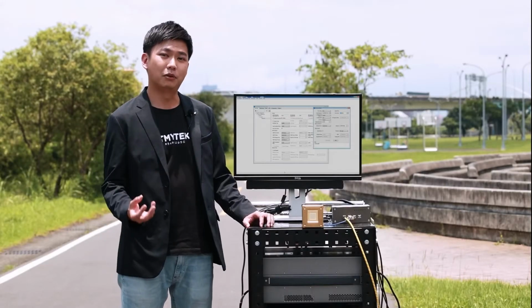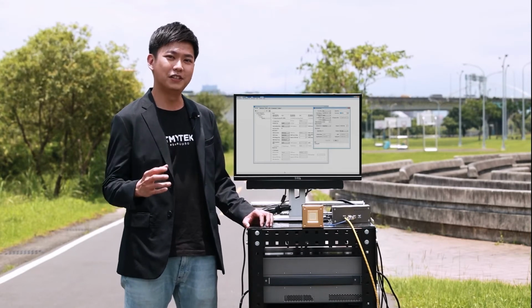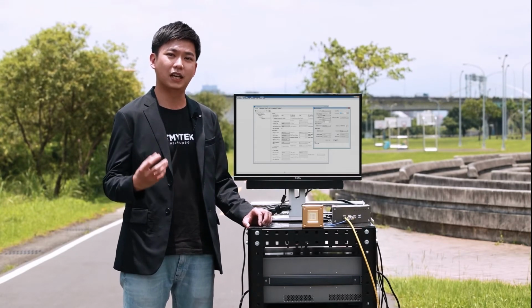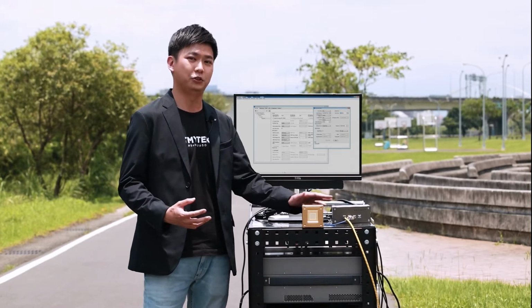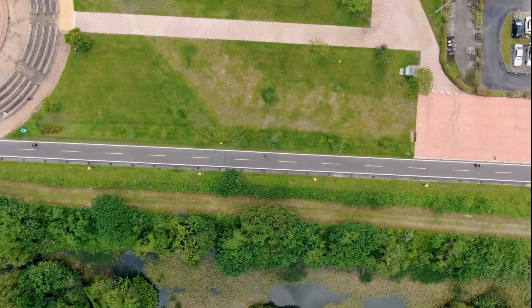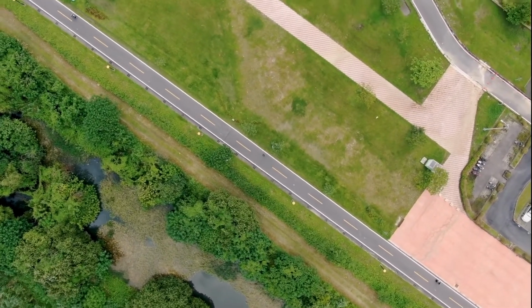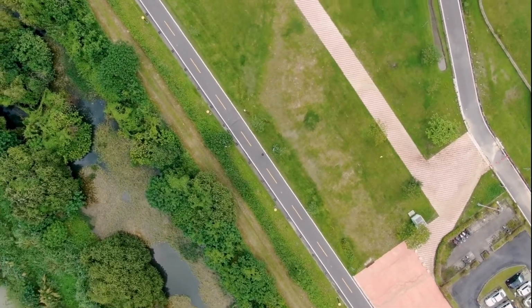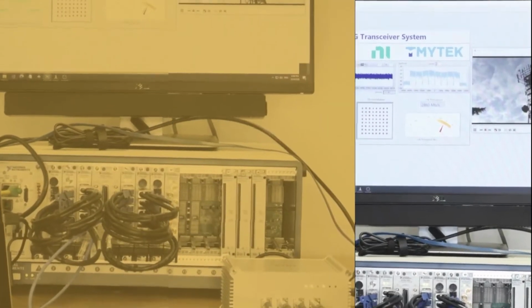In this mmWave transmission experiment demonstration, you can see how easy it was to develop and set up the whole experiment by using TMYTEK's BBox and UD Box. As demonstrated previously, the EVM is around -30 to -32 dB at the distance of 100 meters, and maybe even further. Here is another application scenario.